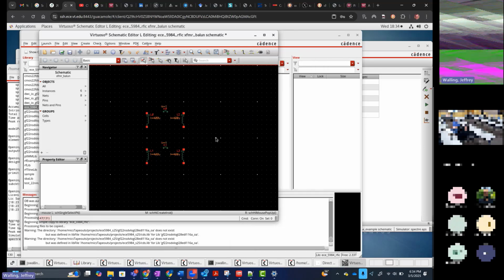Now, there's a reason I'm doing this with 4 inductors instead of 2. I'm not making just a transformer. I'm going to make a balun that's much like the ideal balun that you have in the analog lib kit. So we're going to wire this.